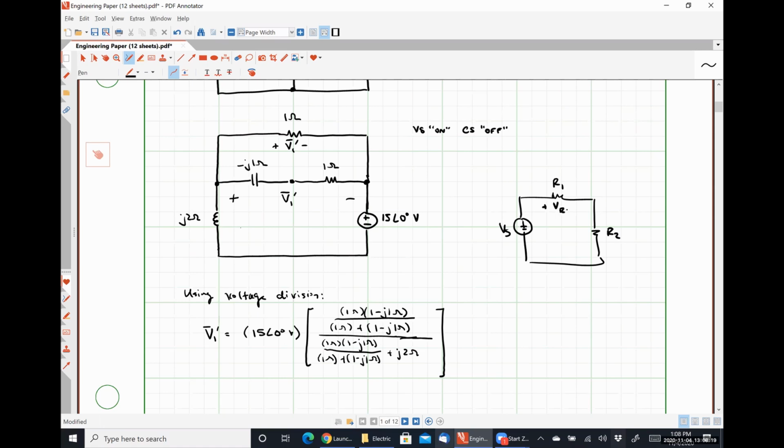The voltage drop VR1 would be defined with a positive polarity terminal connected to the positive polarity terminal of the source, and VR2 would have the same polarity as VR1. We are trying to find the voltage with the opposite polarity because the negative polarity terminal is connected to the positive polarity terminal of our source. So what do I need to do to modify my equation?